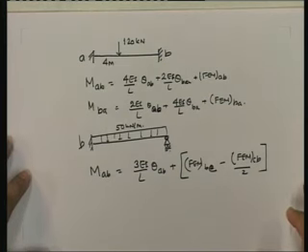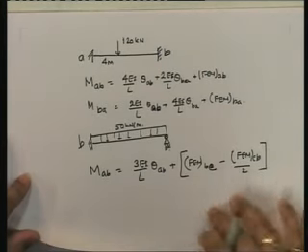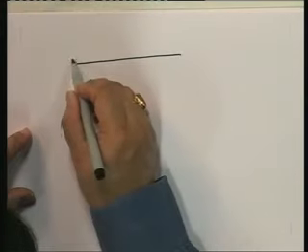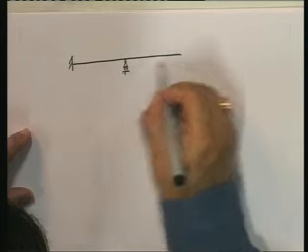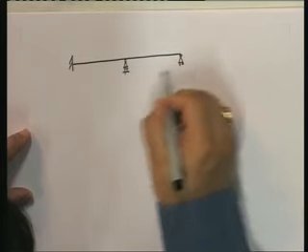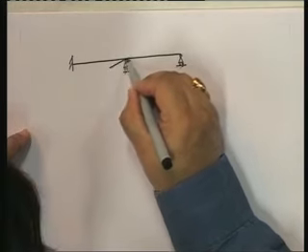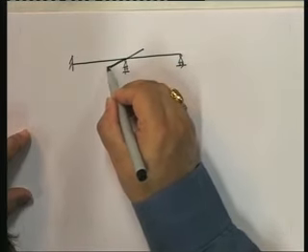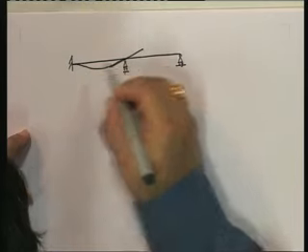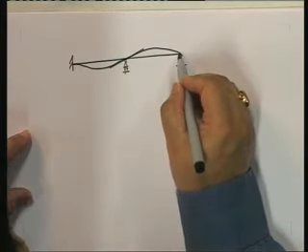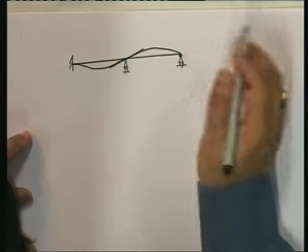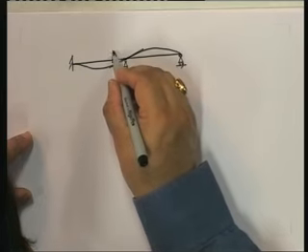Now for theta B equal to 1, let us go through the steps. Note that that's the only degree of freedom. So this is going to become 1. You're going to have a displacement pattern that looks like this, and then over here, note that it doesn't have to go to 0 because this is a hinge. It can take any value. What is the value over there?